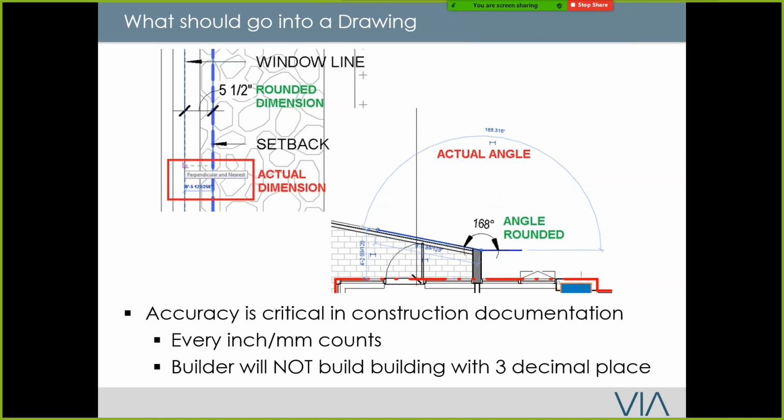The reason why is that if you do a weird dimensioning, it just makes things really hard for the rest. I've seen parts where I have to do a lot of aligning. Let's say this wall, even though it's 168, and then when you do join geometry with the floor below, it does this weird banding, and sometimes it just doesn't want to fit. Okay, just be aware of that.